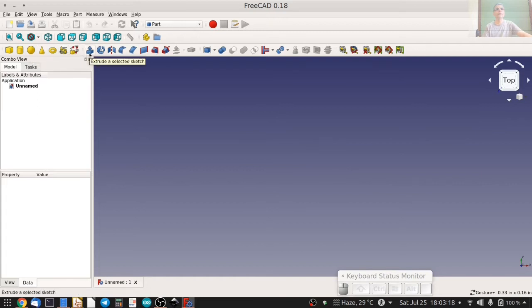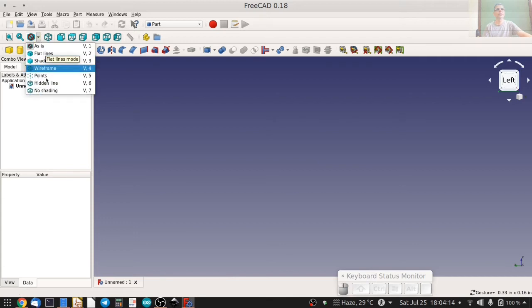And then you can perform certain actions on items that you select, things like revolving or mirroring, adding a fillet or a chamfer, or you can also carry out Boolean operations like making a union or making a cut and so on. This whole toolbar here, the viewport toolbar, lets you choose different views of your object. And there are some zoom buttons and different display options. Let's start off by seeing how we can use that. Let me add a cube.